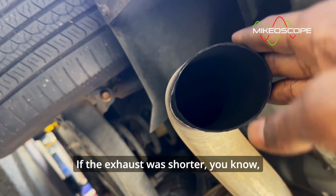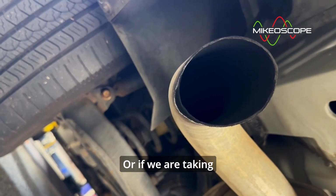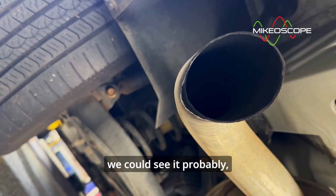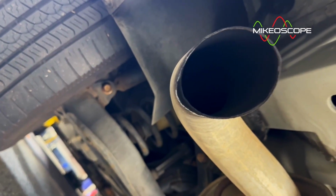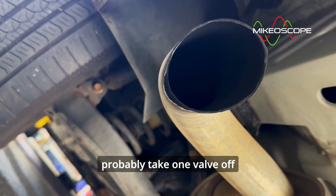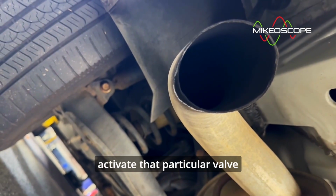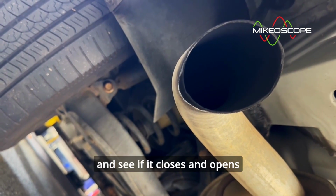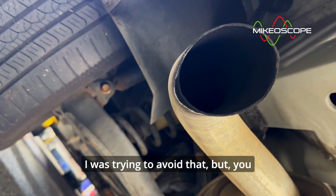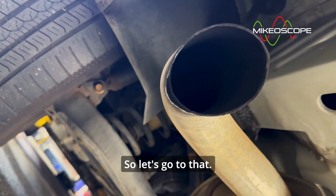If the exhaust was shorter, but how short can it be? Or if we had taken off the oxygen sensor, we could see it probably, but I don't want to do all that. We need to find a different way. So what I'm going to do is probably take one valve off at a time and see if I can activate that particular valve and see if it closes and opens and allows smoke to come through and out of it. I was trying to avoid that, but at this point, this is probably the most conclusive way to figure this out. So let's go do that.